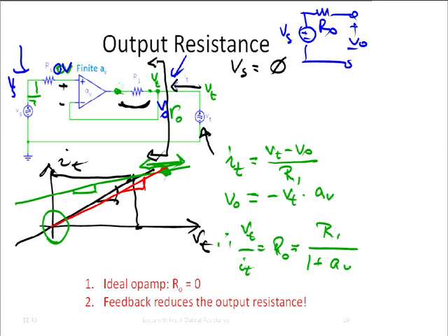when I analyze operational amplifier circuits, and I suggest you do the same, then I usually first assume that the operational amplifier is ideal. And then afterwards, if I have a reason to believe it, what I usually do is I throw the whole circuit into SPICE, and in SPICE you have already seen that SPICE has models for all sorts of real operational amplifiers available. Or you can get it from the vendor. The actual model for the operational amplifier that you're using, that includes all its non-idealities, so the gain is only 50,000, well, that's somewhere in that model. Okay? So then I simulate my circuit with that model for the real operational amplifier, how it really behaves.